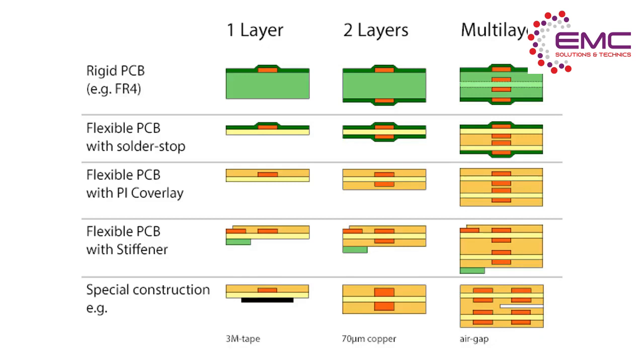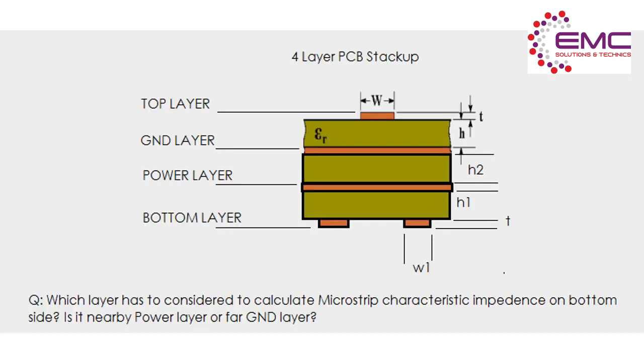Board layers. Proper arrangement of the layers is vital from an EMC point of view. If more than 2 layers are used, then one complete layer should be used as a ground plane. In the case of a 4-layer board, the layer below the ground layer should be used as a power plane. The figure shows one such arrangement. Care must be taken that the ground layer should always be between high-frequency signal traces and the power plane.